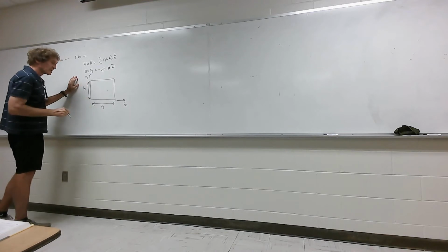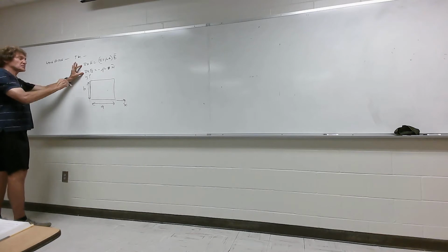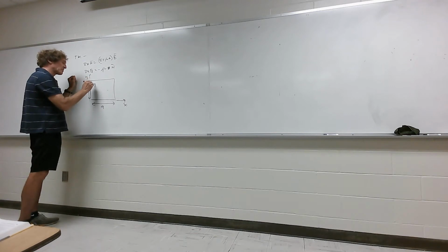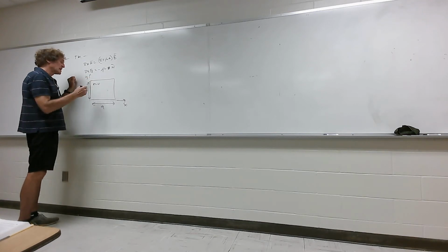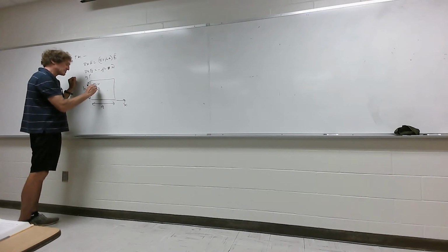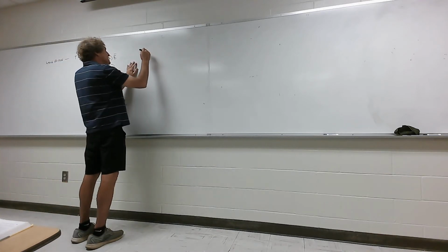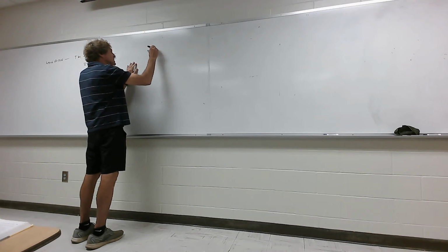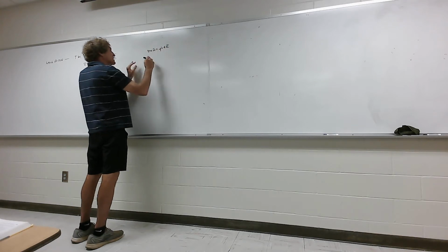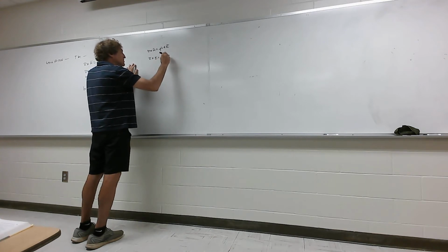They're good conductors. There's a couple things that are apparent when you have these two equations. First, if these two equations pertain to material inside the guide, it's almost always got a sigma of 0. It's always very low loss, and in general, it is lossless for all intents and purposes. That means these two equations become curl of H equals j omega epsilon times E, and curl of E equals minus j omega mu times H.